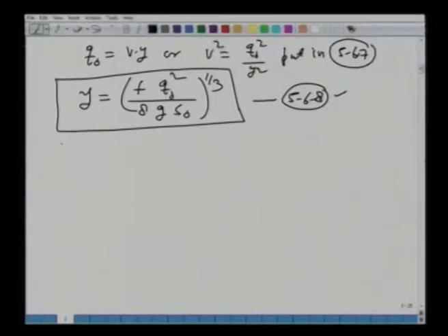Okay. Now, this is for laminar flow. So, this is assuming the sheet flow or the overland flow during the rainfall runoff process is laminar. What happens when the velocities increase, or the steepness of the overland topography is very steep? If that is the case, then the velocities will be high and the laminar conditions will change into turbulent. Okay. So, in that case we will have to analyze it slightly differently.